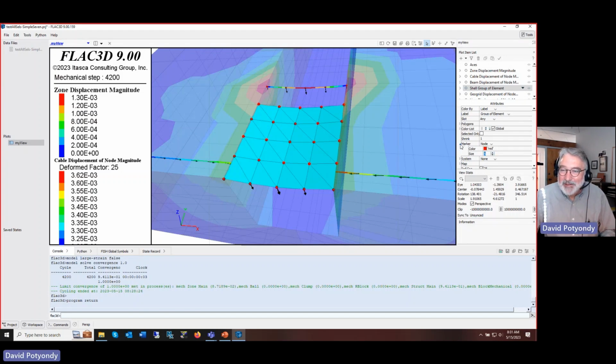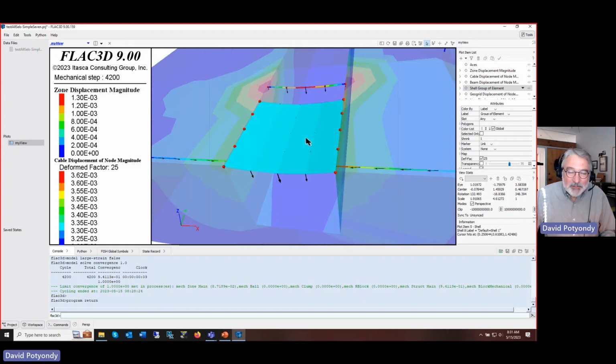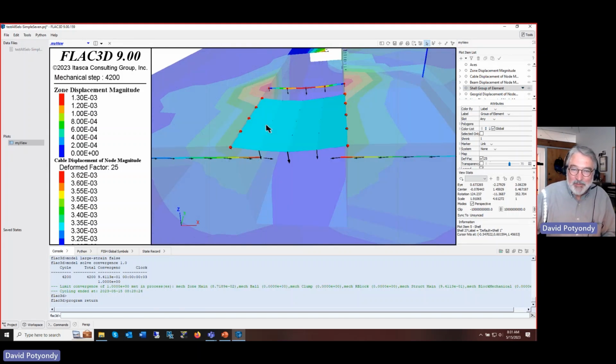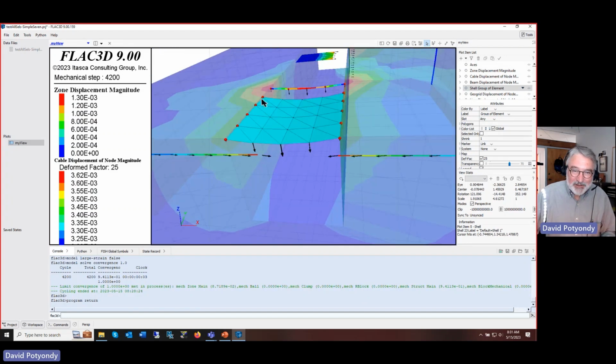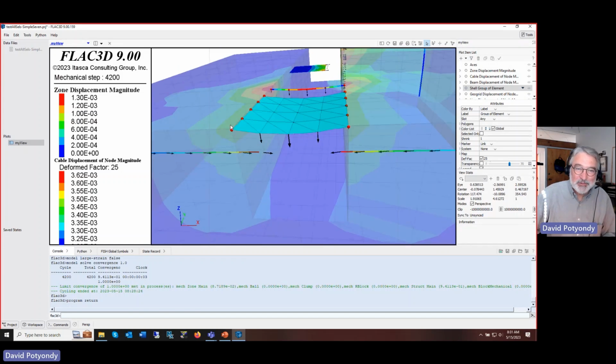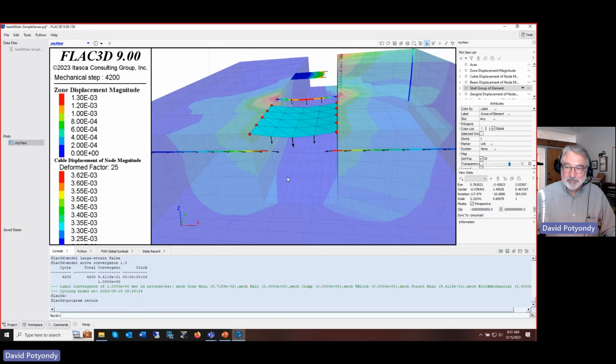All right. What other markers are there? There's one that's called link. And these we'll talk about. This is the low level way that the nodes can interact with the zones. And so you can see there are links on those edge nodes that are linked to certain locations inside the zones. The structural elements essentially just get created and they will automatically link themselves to zones that they're in. They're linking themselves in a general way. They can be at any location in a zone. It has nothing to do with grid points. Okay.